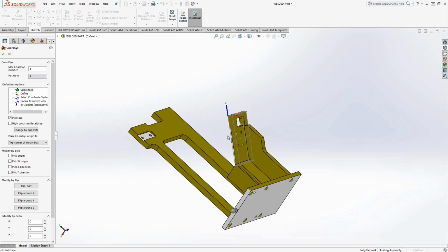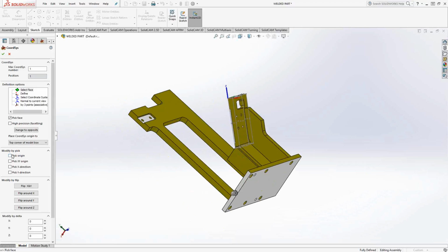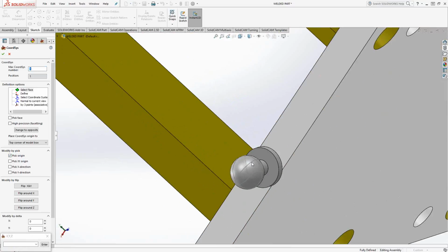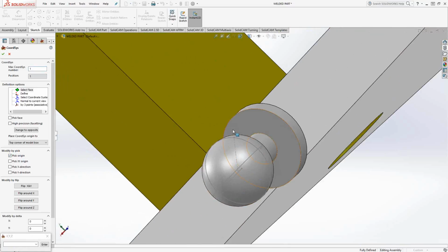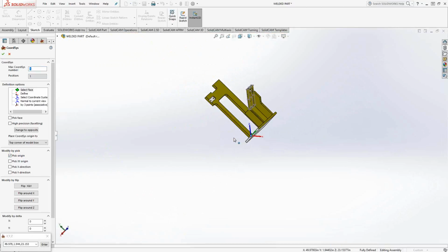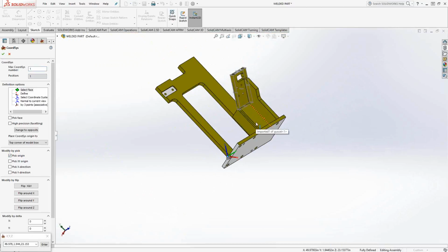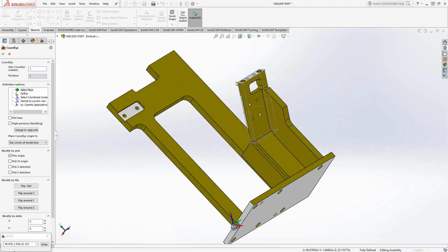The origin is going to be on the Toolball. So I'll go back to the left side, click on Pick Origin, scroll down here, and there is the top of the sphere that we created with all those sketches. So I'll just say Pick Origin there. Now that I have that there, it's just a matter of setting up which direction is my X and my Y. So let's say, for instance, X positive is to the left of the screen.